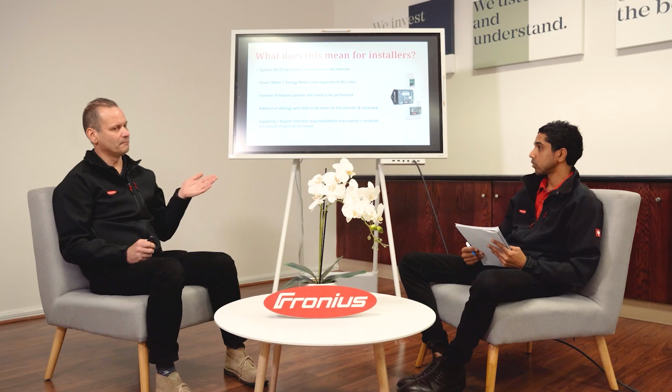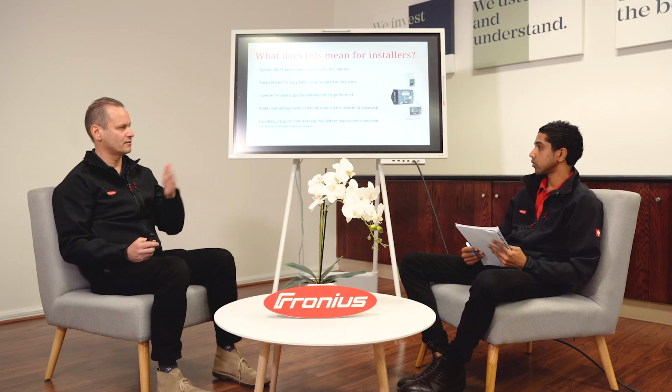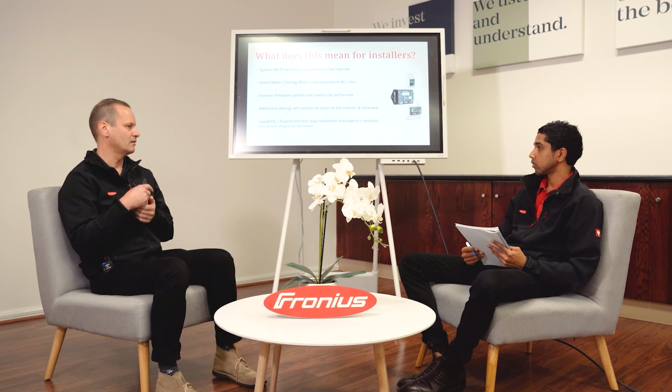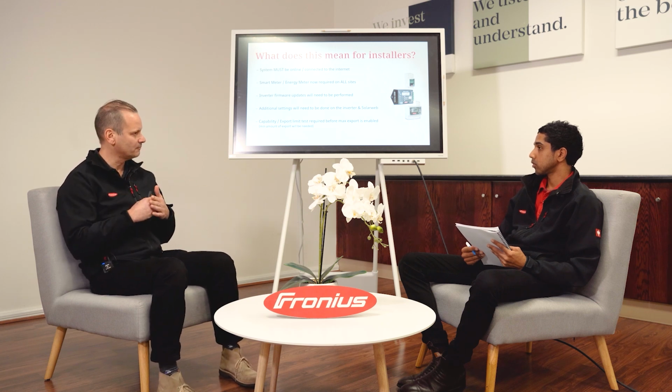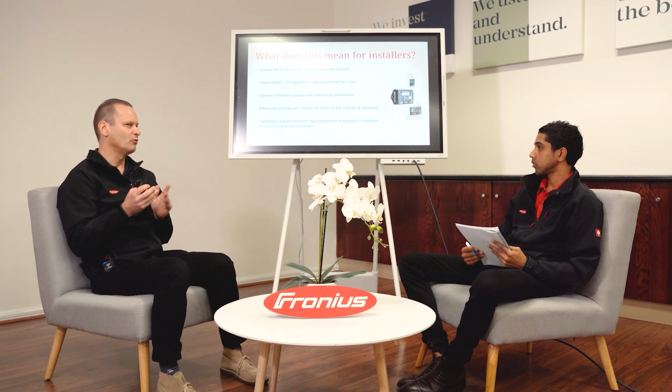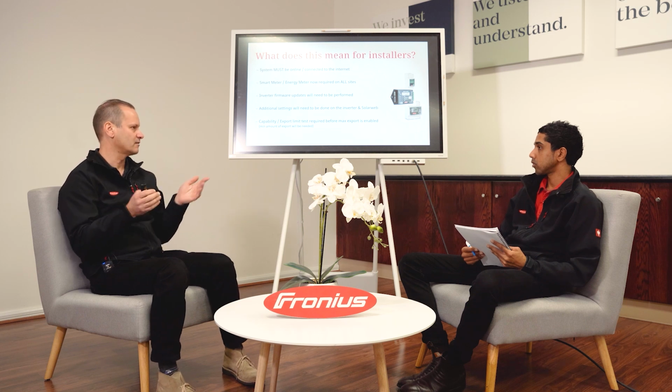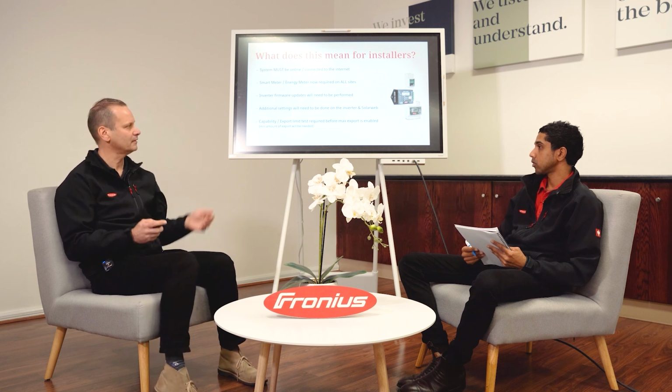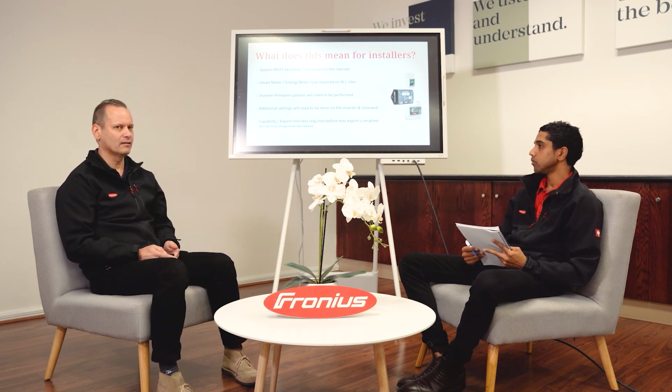It's not 100% known how that's going to be done, if it's in the DNSP app or in their portal, etc. But basically what it'll entail is, if the system's exporting, the utility server will issue a zero export command. It'll check the telemetry data and make sure that it's doing what it's meant to do. It'll hold that for like 5 minutes and then release it and see that the inverter ramps back up again. So it's kind of testing that functionality.